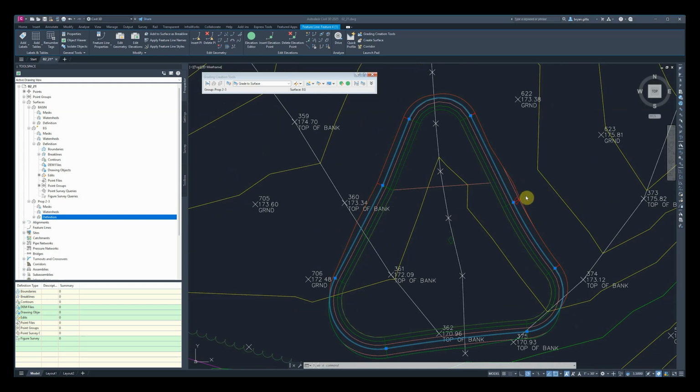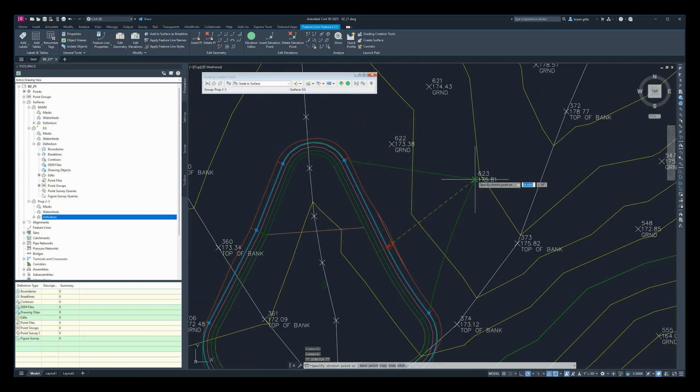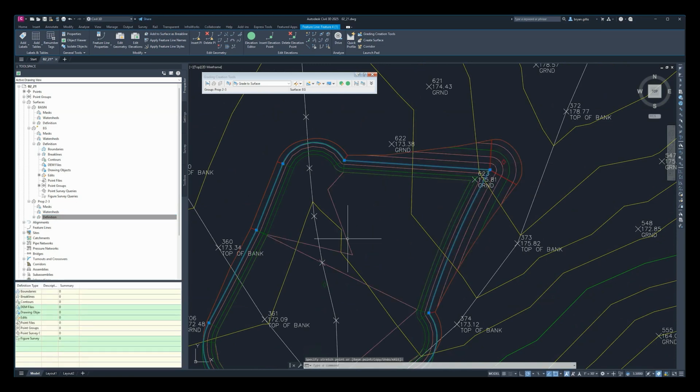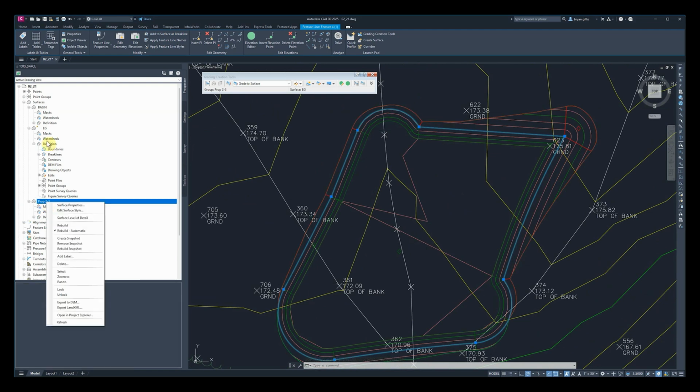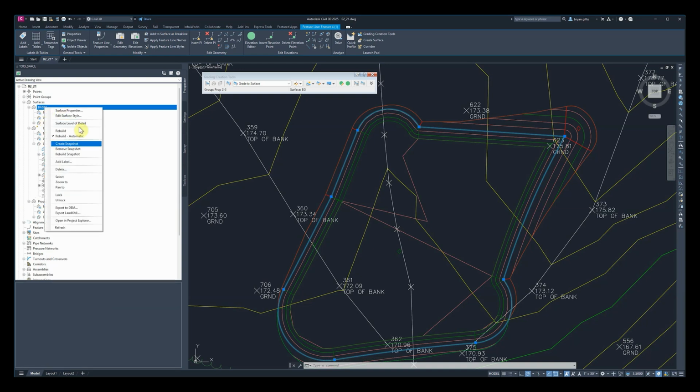What I want you to do is grab that point next to the red diamond, and then we're going to drag it just kind of over here. We'll say to 0.623. Go ahead and just click a little bit past that, and you're going to see it's automatically going to regenerate. If it doesn't, you can go to Basin and then hit Rebuild if it's not done automatically. But you see that, and we see this automatic restructuring of our cut and fill